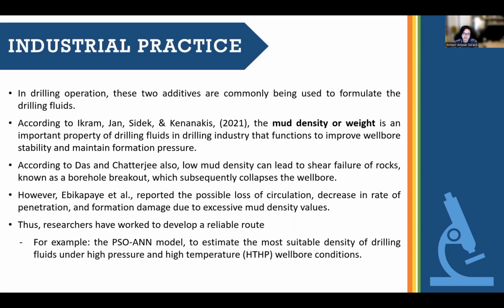The first point is, in drilling operations, these two additives are commonly used to formulate the drilling fluids. According to Ikram, Jan, Siddiq and Kenanakis 2021, the mud density or weight is an important property of drilling fluids in the drilling industry that functions to improve wellbore stability and maintain formation pressure. According to Das and Chatterjee, low mud density can lead to shear failure of rocks, known as borehole breakout, which subsequently collapses the wellbore.